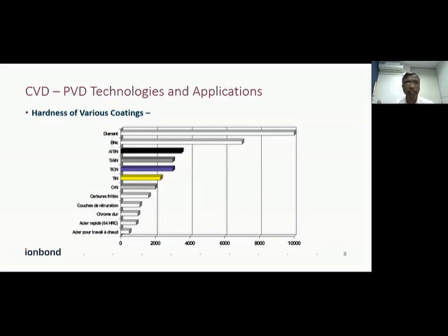That is the hardness of the base material. But as we start getting nitride coatings, the hardness increases by 2 or 3 times. For example, the basic chromium nitride or titanium nitride coatings, which are the basic coatings in the industry,